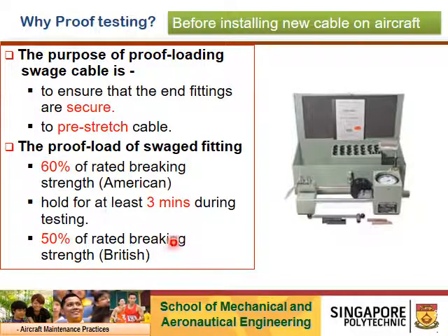So the cable manufacturer will actually manufacture the cable and do a proof loading on the swaged cable to ensure that the end fittings are secured and also to pre-stretch the cable. So what is the loading type? 60% for American, 50% for British. And when you do a proof load test, you need to hold the cable for at least 3 minutes.